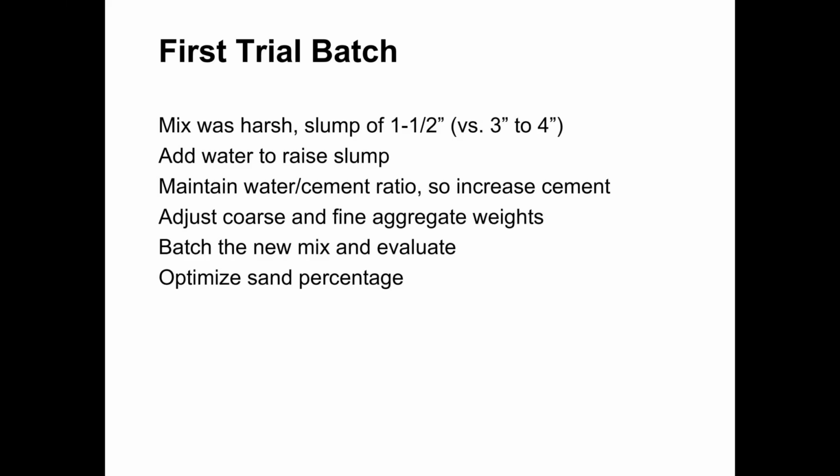But I draw your attention to this just so you're aware that there are some ways that we can go about economizing our mix. There are other ways that we have either already talked about or will talk about in the class, but this is one of those tools that you have in economizing a mix design as part of the mix design development process, and that is determining the optimum sand percentage, which typically is going to give you the least amount or minimum amount of cement that's needed in the mix in order for the mix to achieve the desired strength performance.